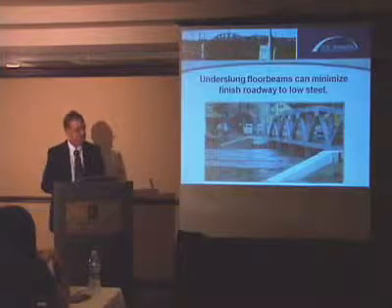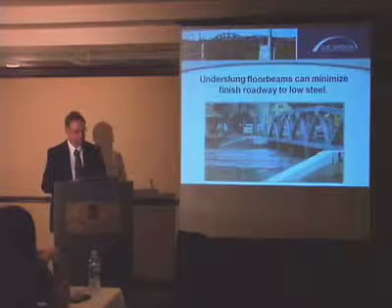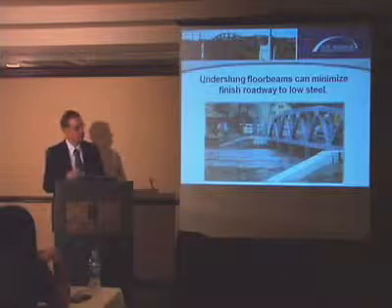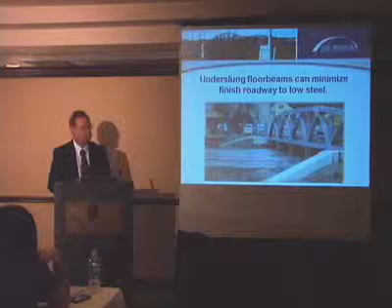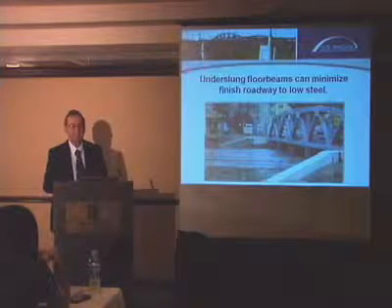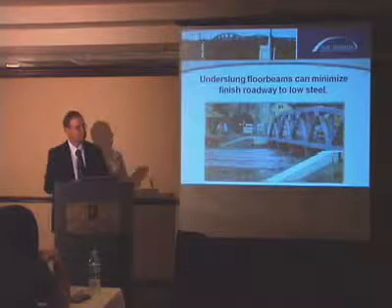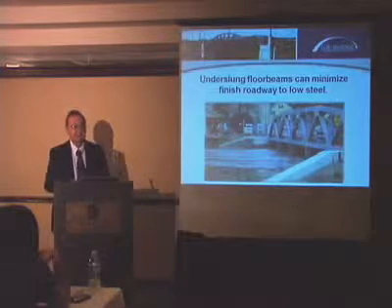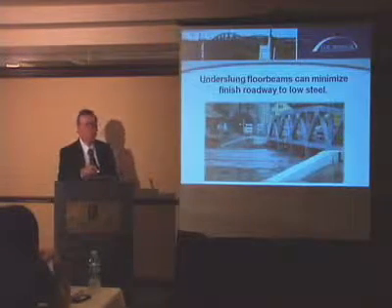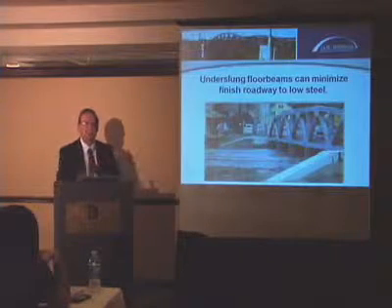I've always had a lot of debates with engineers over this method. A lot of them say the low steel for the floor beam is the lowest point you want to use, but you can still get about 2 to 3 feet more water. Debris will hit on the ends of the floor beam, and a lot of times it'll wash and continue on around it.